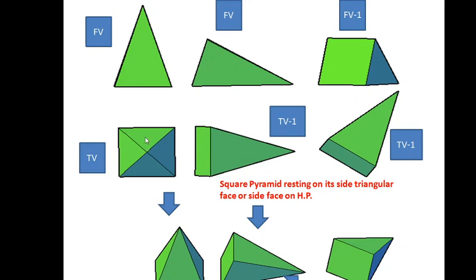So when I extend this in the upward direction, of course, that gives the height of the solid. So I can extend the height with respect to the body axis. Extend the center in the upward direction, so we can draw its height. Then join these corners with the apex, and you will get the front view. Later on we have to see what is given in the problem.